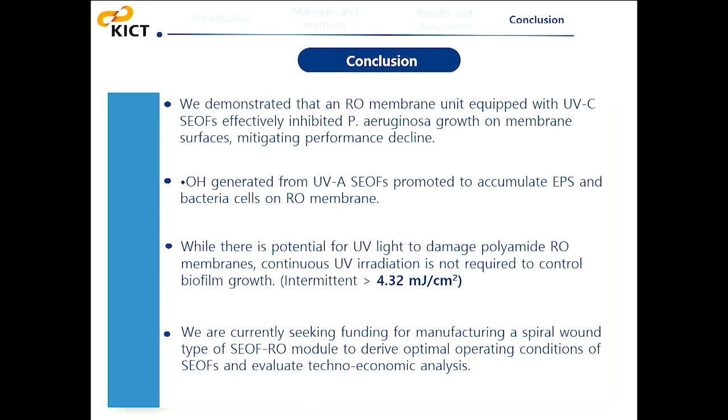While there is a potential for UV light to damage the polyamide membrane, continuous UV radiation is not required to control biofilm growth. So we are currently seeking funding for manufacturing a spiral wound module of side-emitting optical fiber and reverse osmosis membrane to derive the optimal operation condition of side-emitting optical fiber and evaluate techno-economic analysis.